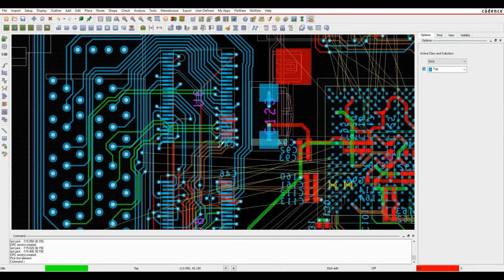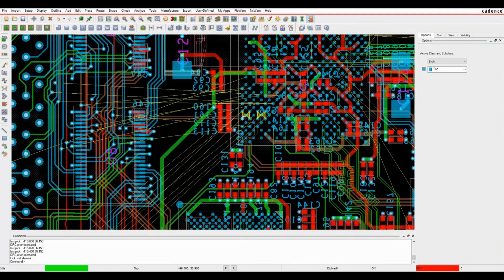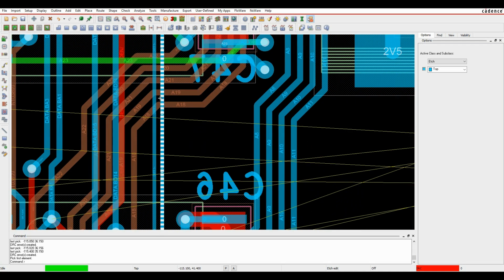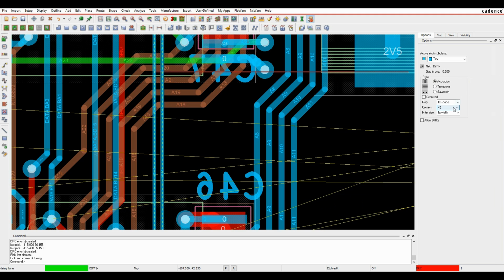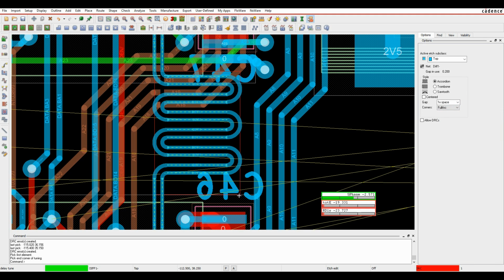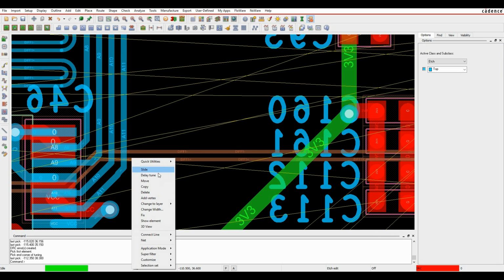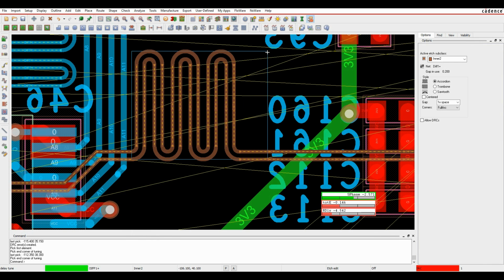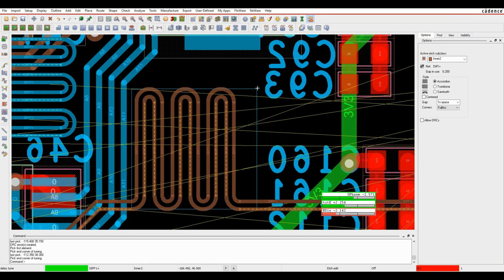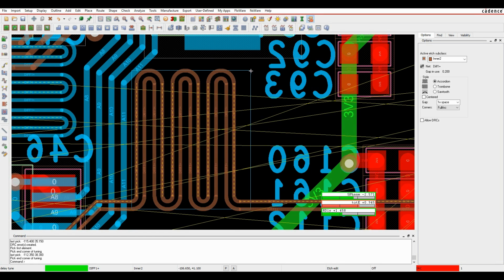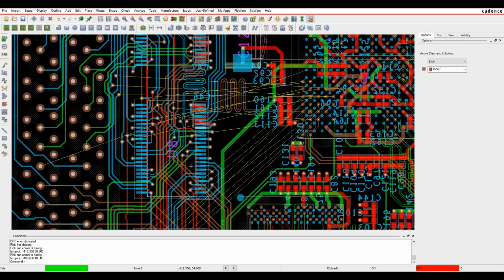We'll just go back into etch edit mode. I've got a couple of DRCs here for the length matching on this differential pair. So we'll hover over the trace and we can do a right click delay tune. Let's set the options to maybe full arcs, and I can get some arcs coming in to try and sort the length out. I'm meeting the phase tolerance but not the other two. I haven't got enough room in here, so we'll move to a different part of the PCB and continue with the delay tune. And you can see the heads-up displays going from red to green, red to green. When I get them all green, I know I'm meeting the constraint and I'm good to go.